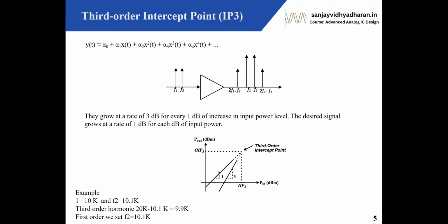Okay, these signals. So if you plot and extrapolate these graphs, the 1 dB plot and the third harmonic plot, the gain of this and the gain of this, okay, these two. If I plot the gain of this and gain of this, and if I extrapolate, they will meet here, okay, at this particular point, the signal strength of this and this frequency will be the same, right? I can't give an input signal more than that, okay. After that it is going to deteriorate my signal, because this unwanted signal will have more strength than the wanted signal.